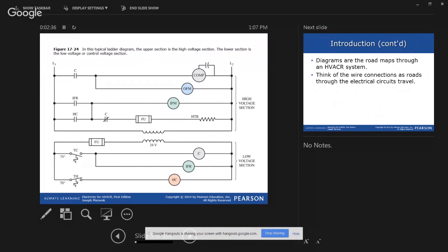Usually it would be indicated. The long and short of it is that if this was actually on a unit, and we will check today, we will see what the voltage is between here, and it'll probably have a little indication somewhere that the line to line voltage is either 120 hot to neutral or 240 phase to phase.